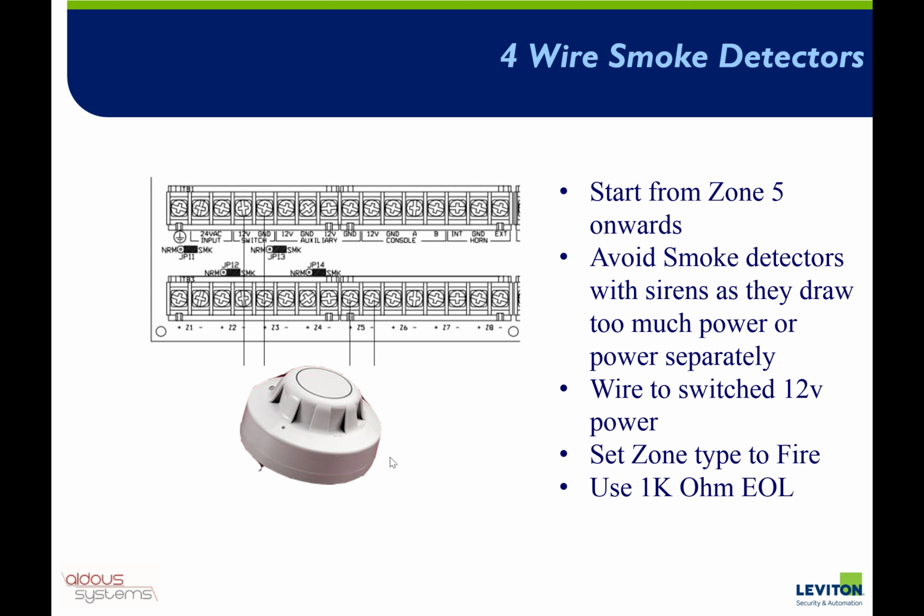Smoke detectors, very useful to add smoke detectors to the project. Obviously, a lot of people just have battery-powered smoke detectors where batteries get removed, and when the batteries get low, it starts beeping, and people take them out. Whereas these smoke detectors off the panel are permanently powered from the panel, and of course, battery backed up from the battery backing up the main panel.